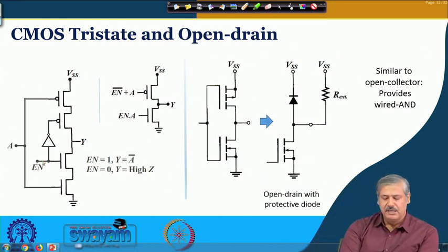So, in the inverter this En is 1. Okay. So, this NMOS is on and this is inverted means this is low. Okay. If this is high, this is low. This low means this PMOS is also on at that time. Okay. So, the output at that time will totally depend on whatever is the input. Okay. So, when En is equal to high, this is on, this is also on, and output follows the input. There is the inverter logic, so it will be the inversion of it.